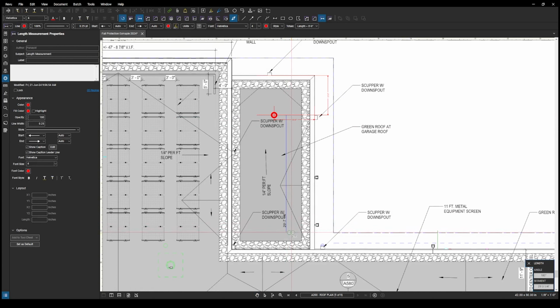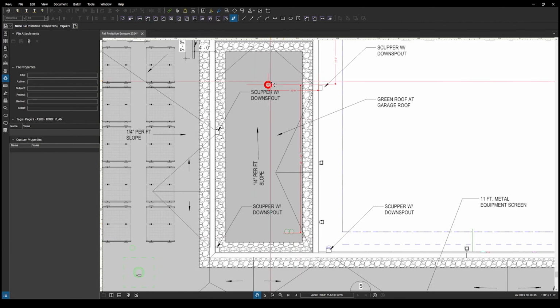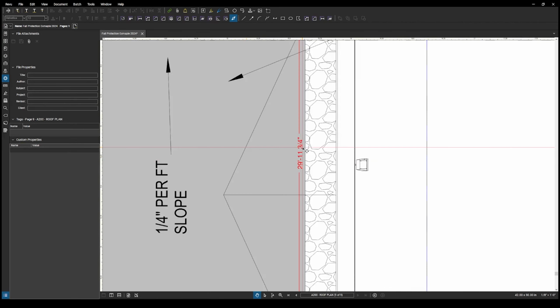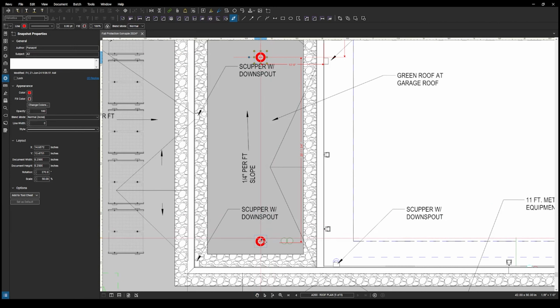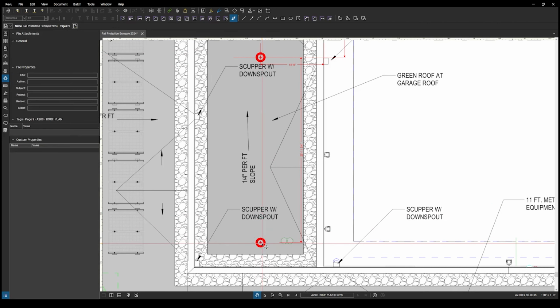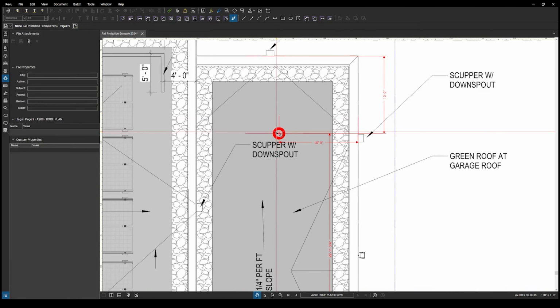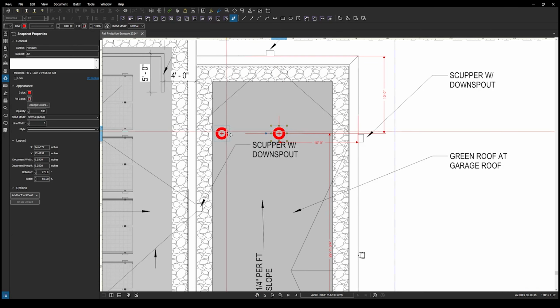We set our anchors along those measurements. Now, the only caveat is the length between anchors cannot exceed 30 feet. So this one anchor is technically unnecessary in the center because our span between the anchors on the long side is less than 30 right here. But we'll just redo that really quickly and it should be all good.